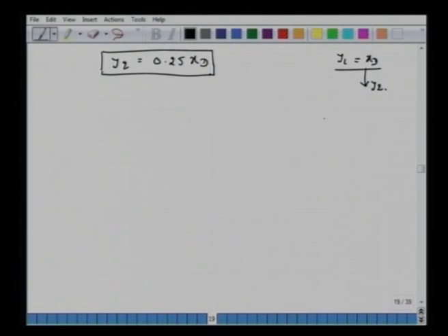Now let's do it for the third stage. Okay. So stage 1, stage 2. Now we have this stage 3. Mind you, this feed enters here. So this composition and this composition. What is this composition? This is y3. And what is this composition? x2. Now still we can write down these expressions between x3 and x2. Alright. So this y3 and x2, the composition here do not change.